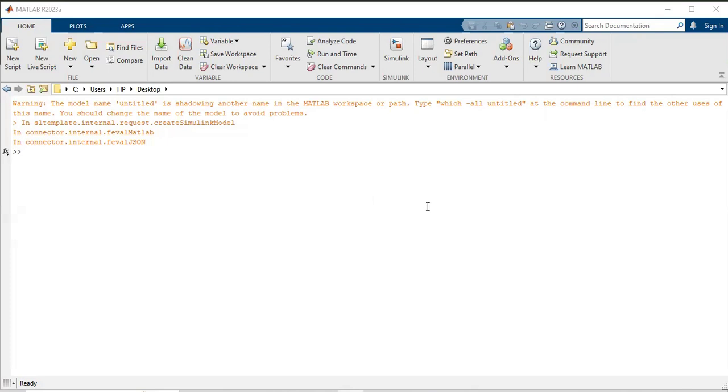So when two converters are operated at the same time, we will be having circulating current flowing in between the two converters. The current may damage the devices. So in order to limit the current, we need to have a reactor between the two converters. So the difference between the two modes is that in non-circulating current mode, only one converter will be operated at one time, but in circulating current mode, both the converters can operate at the same time. To limit the current, we need to have the reactor in between the two converters.